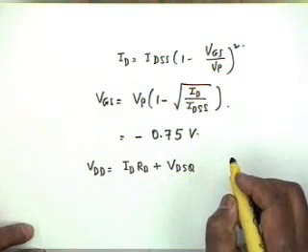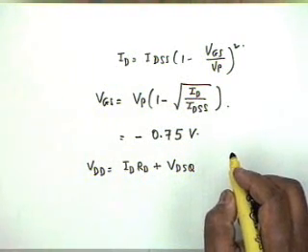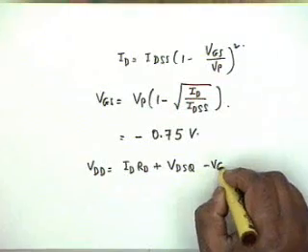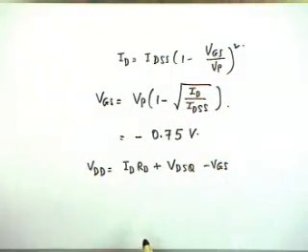Then when you go to S, you can then go to the ground via VSG, which is minus VGS. Agree? Is this equation clear? We come from VDD, ID RD, VDSQ, then from source to ground via gate, VSG, which is minus VGS.